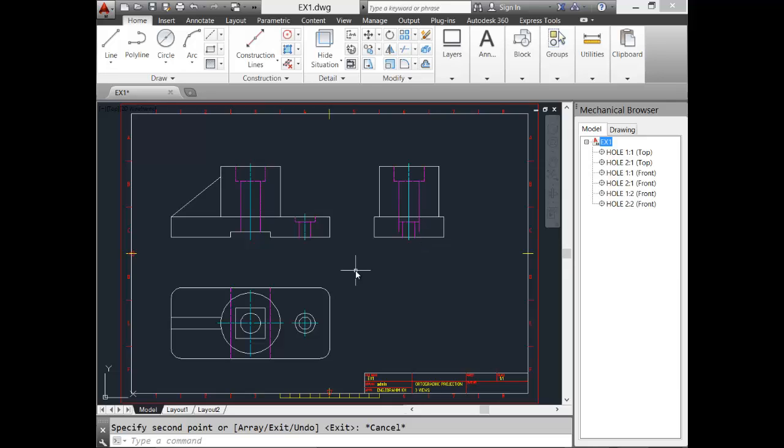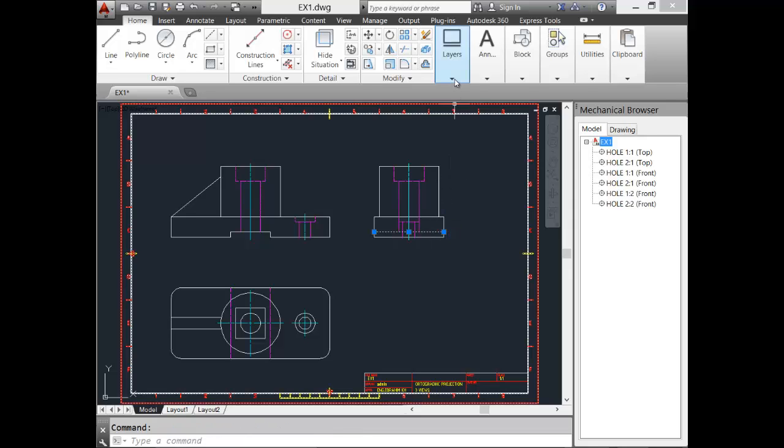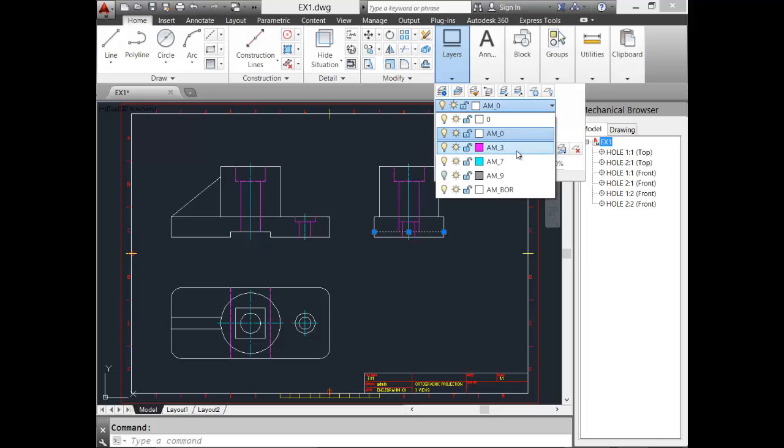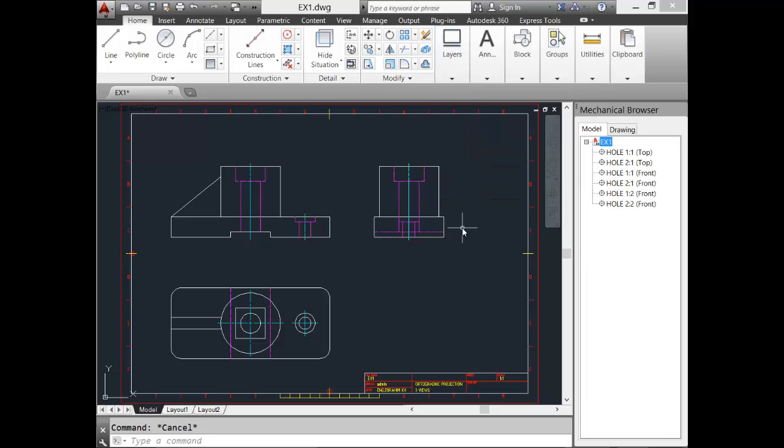The last thing I will do, or before the last thing, I'll take a projection of my groove. When I'm looking from the front, I can't see my groove, it's up by 5 millimeters. I'll take a projection from my groove to the end. It comes here from the end to the end. I'll trim, enter, and remove the extra line. I'll change this to hidden because it's inside. I'll go here to my layers, to my hidden layer, and I'll hit escape.